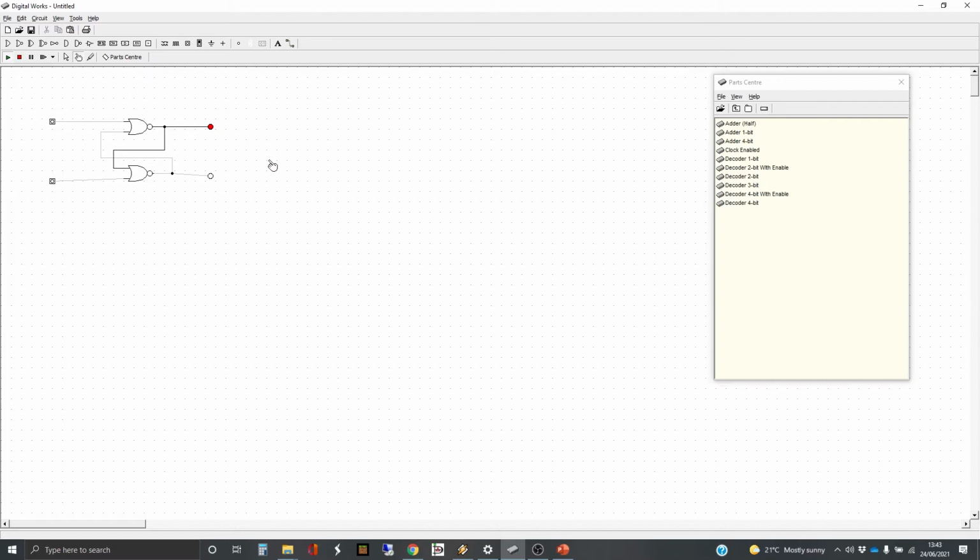So this is giving us already an output of 1 at the upper output and 0 at the lower output. And let's use one of the inputs and see what happens. If I hit that input, it switches these two outputs, so that becomes low and that becomes high. When I stop having that input, then it stays as it was.